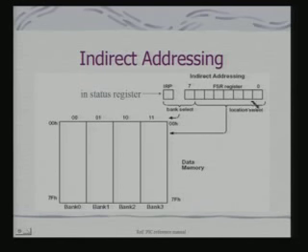Now, this value you need to load in the FSR register through an instruction. The bank select is via the IRP bit, which is part of the status register, and the 7th bit in the FSR register. The remaining 7 bits are used for selecting the offset in the bank.